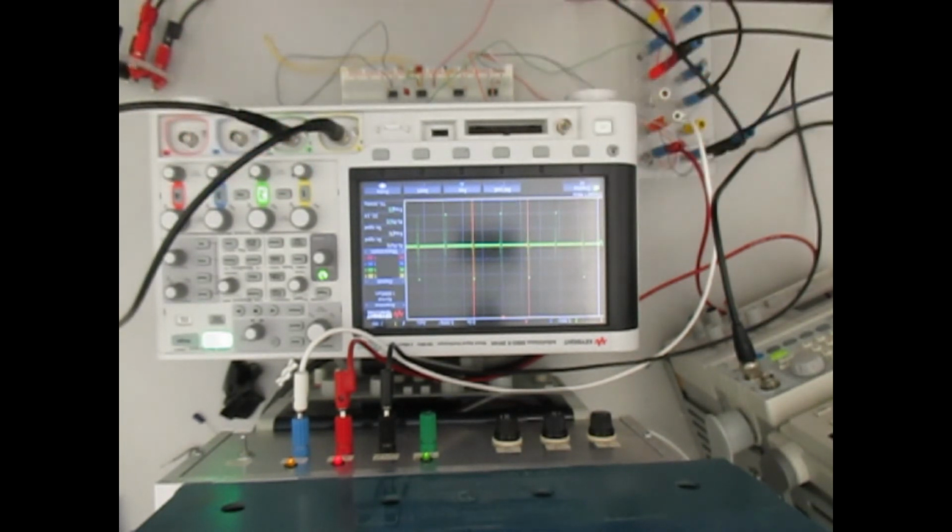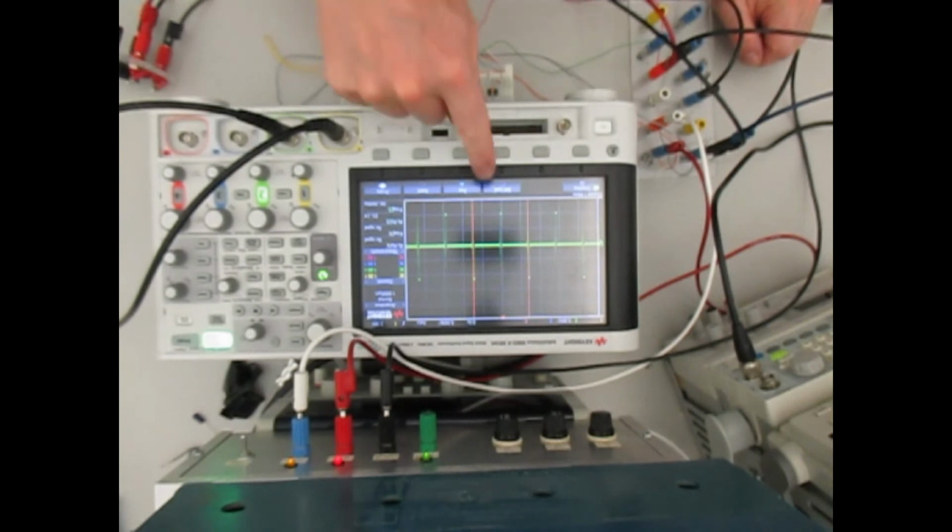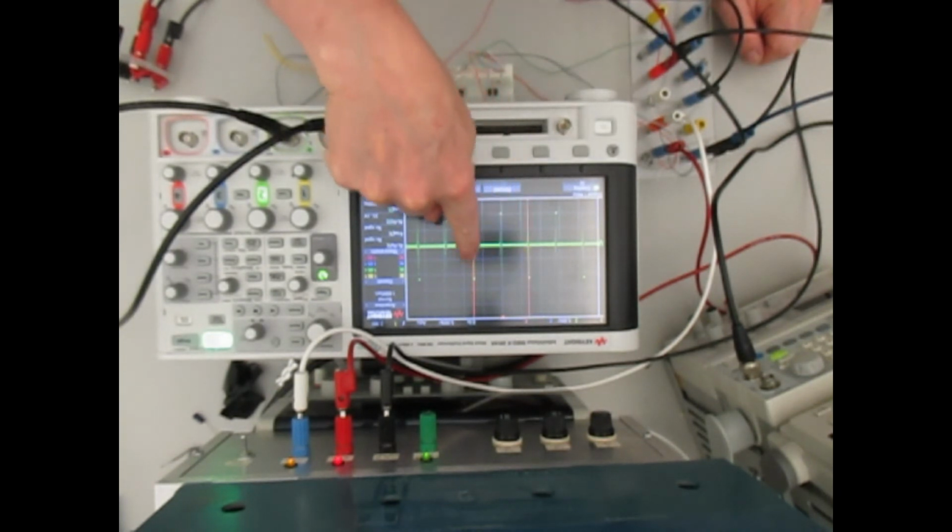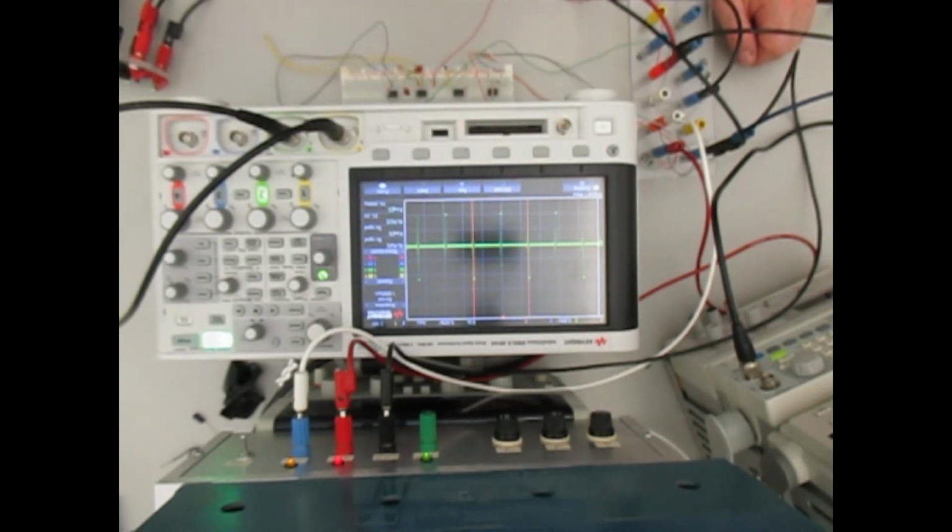And I mean, this is really hard to see, but you can see there's like these little spikes here, right? And that's what we want to see. That's the derivative of a square wave input. Okay? So then if we change to our triangle wave, the triangle wave should be a square wave output.